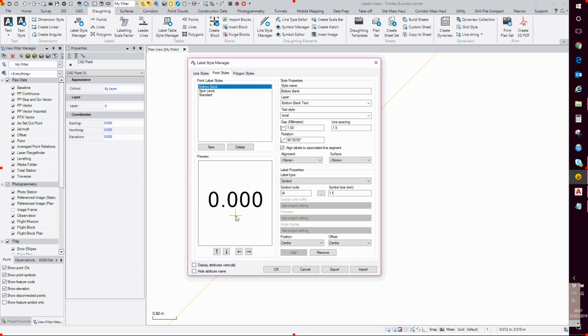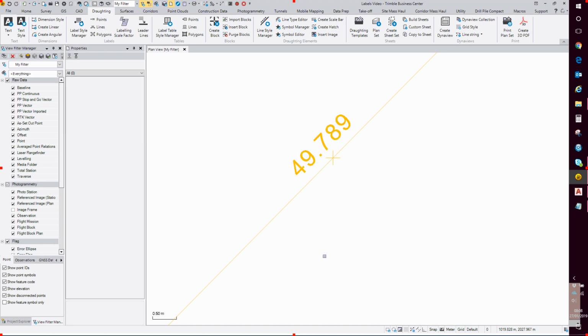So that point symbol is being pulled actually from a font called symbol.shx. And it's a font that TBC uses and CAD programs can use as well. The problem may arise where that font file isn't present with AutoCAD. Of course, one solution is to transfer the symbol.shx font and place it in the AutoCAD fonts directory.